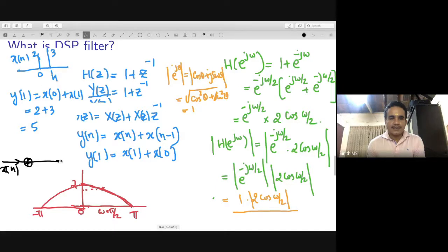You take x[n]. How do you get x[n-1]? You take a delayed version. Delay is represented by z^-1. Then you can take that from here, and with a delay like this it will be x[n-1].